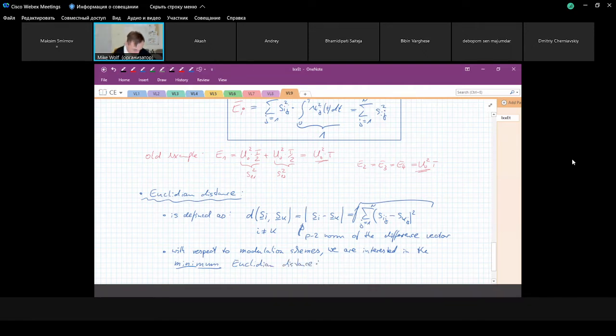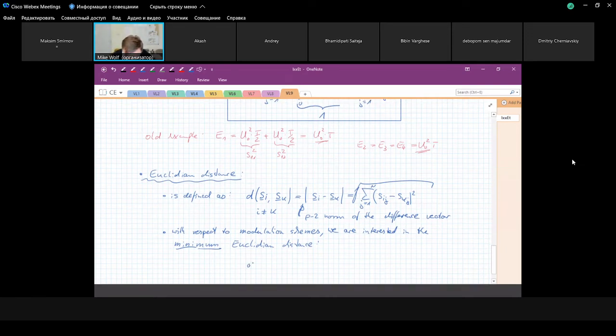And we write this as d min, as in the figure. This d min is just the minimum value of all these Euclidean distances. So we take a look at all possible combinations of different vectors, look for the distance between these two vectors, and choose the minimum.